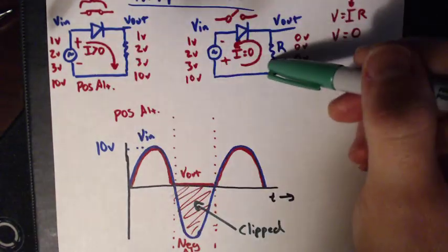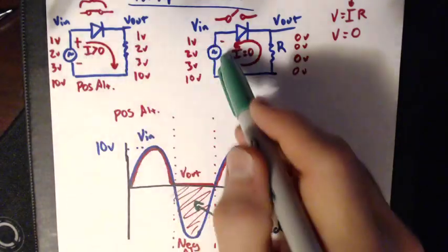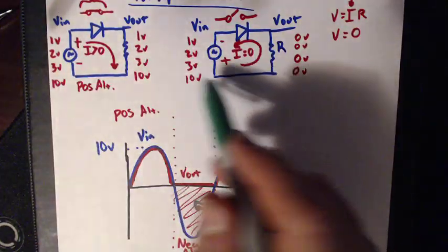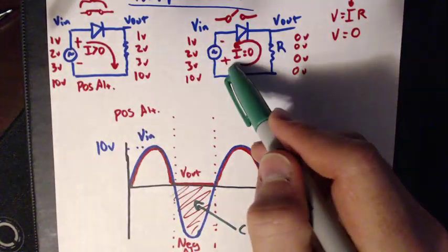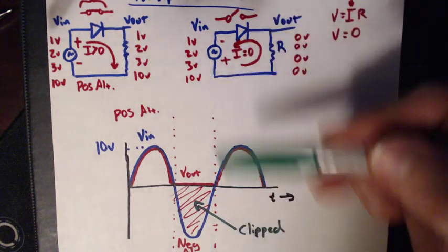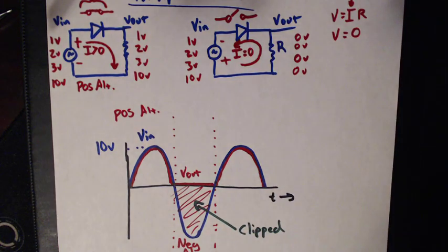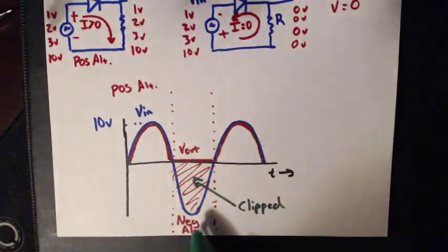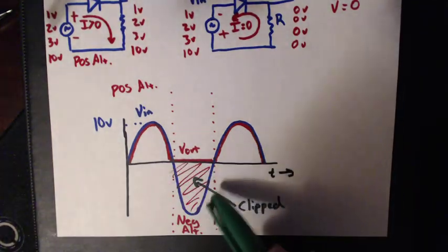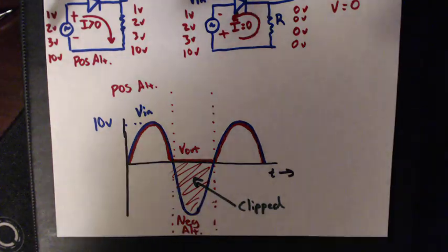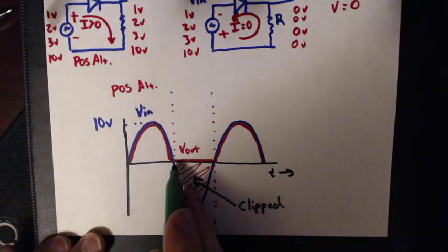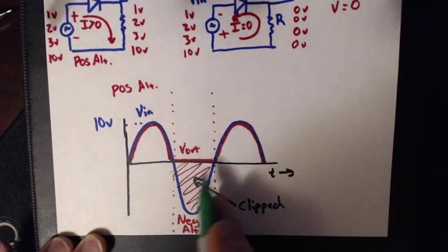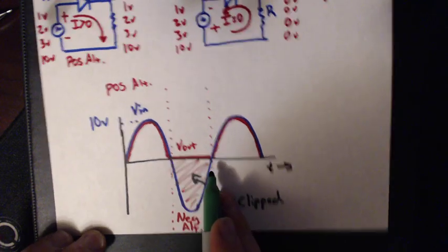The circuit remains the same, but our AC switches between the positive alternation and the negative alternation, 50-50. Does that half the time. Now, what is it that we are losing here? Well, we're clipping all negative voltages. Our V out always stays at 0 whenever the applied voltage goes negative.